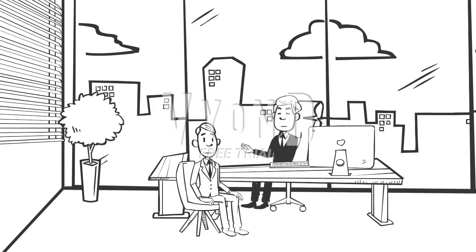The wide spaces also lock in excessive movement and transportation waste. As for the garden in the factory, people never sit at these tables and chairs and they simply provide a detour for transporting goods to the next process. So, when designing a factory layout, forget aesthetic beauty and focus on function. At TXM we believe a well-designed lean production cell operating smoothly is actually a thing of beauty in itself.